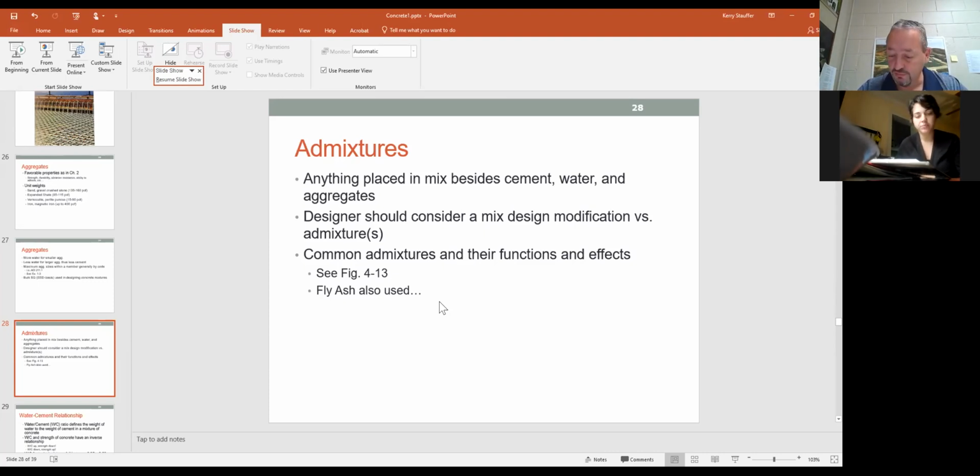Yeah, retarders are on the top of page 103, would be the opposite. So if you had a whole lot of concrete to finish and you only had a few laborers, it may be a problem that you wouldn't be able to finish all the concrete in time. So maybe in part of it, you would put a retarder in. And so that would actually delay the setting time and enable your crew to finish the first part and then get over to the second part, something like that.